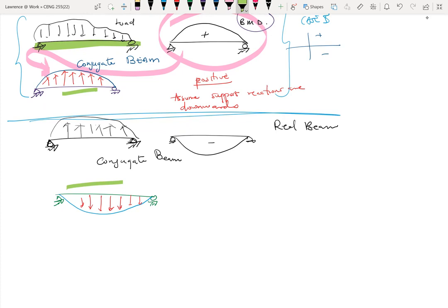All right. So we are working with the fact that we position the bending moment as loads on the conjugate beam in the position they were in the real beam, and that indicates that all the directions of the load are moving away from the beam. Okay. So again, let me call this a negative. Then again, we also assume that our reactions here are downwards, in the same vein as this right here. And then you solve for whichever points of interest that we have.